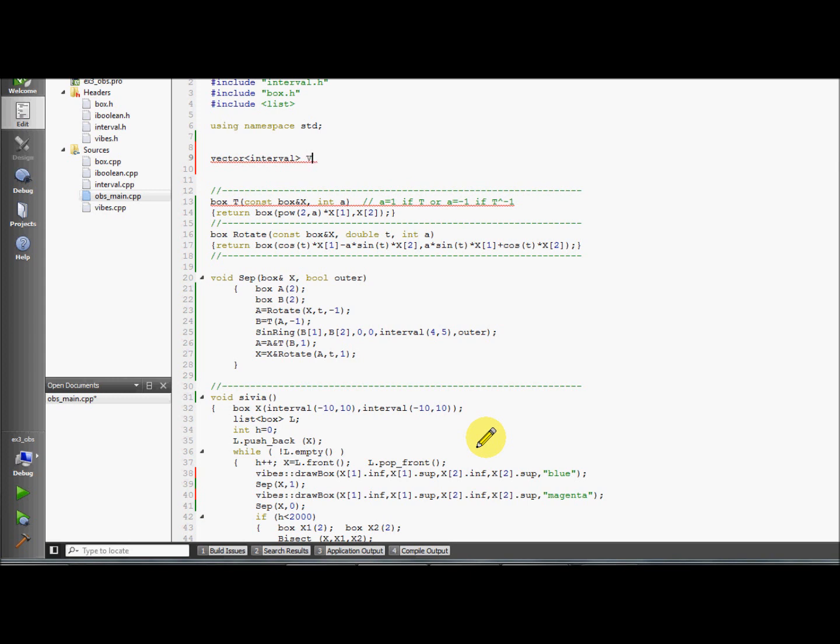I will have the speed, which is known by my robot. You know its speed. It knows its heading because of some compass, and it knows some distance. So V and theta correspond to the proprioceptive data from the robot, and D is the only exteroceptive data.